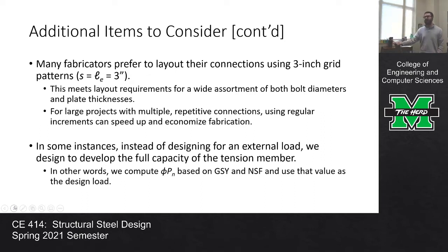And so for those repetitive connections, a lot of times the fabricators will go with 3-inch spacing. 3-inch spacing meets the layout requirements for a wide array of bolt diameters and a wide array of plate thicknesses. And so it's a nice sweet spot value that tends to get used quite a bit.